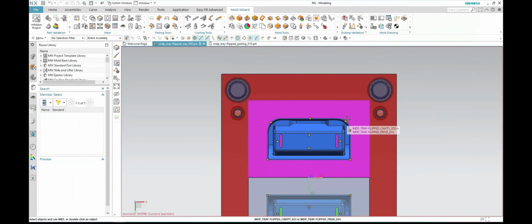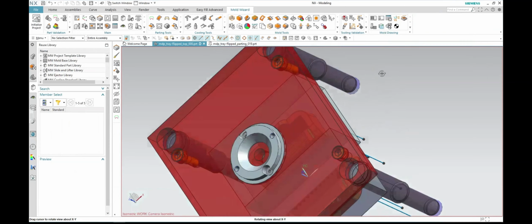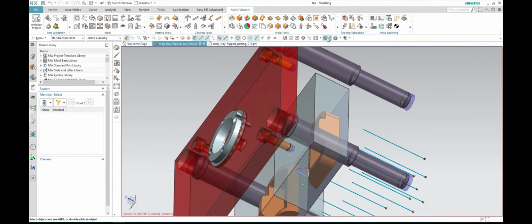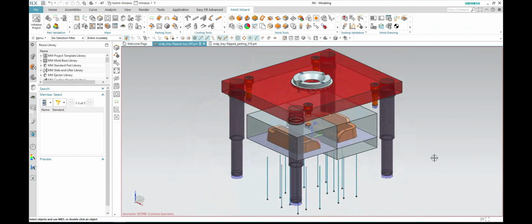Give it some time, because we're going to create those ejector pins for you, and you can see the ejector pins that it created. If you didn't untick the symbol, you won't be able to actually see it, which is quite important here. Now I need to post-process it, and this is quite an important stage. I haven't defined the length in here, which is why these are short.